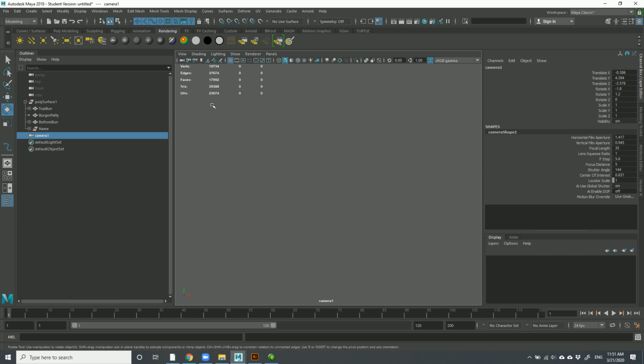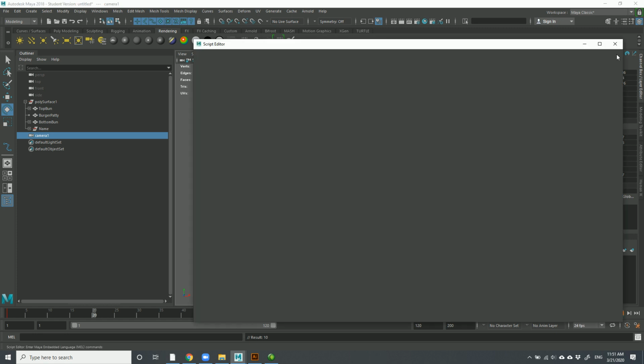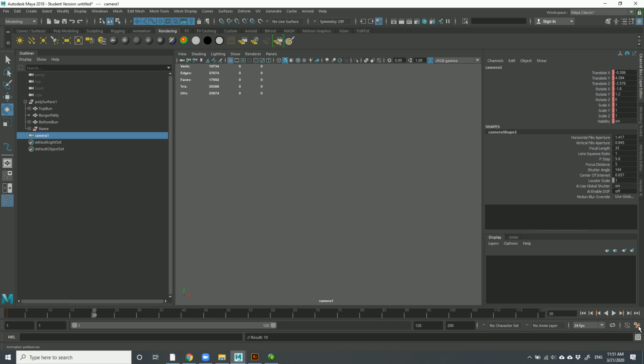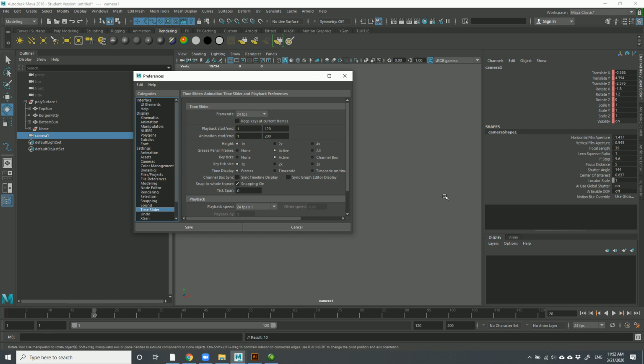If I press S to set a keyframe, that's setting my very first keyframe, and then maybe, let's see, we are at 24 frames per second, which is the default, the film frame rate. I can change that for video if I want. I'm going to go to this little orange man in the bottom right corner of your workspace, and change this to 29.97 frames per second, either that or 30 frames. This is like video here.